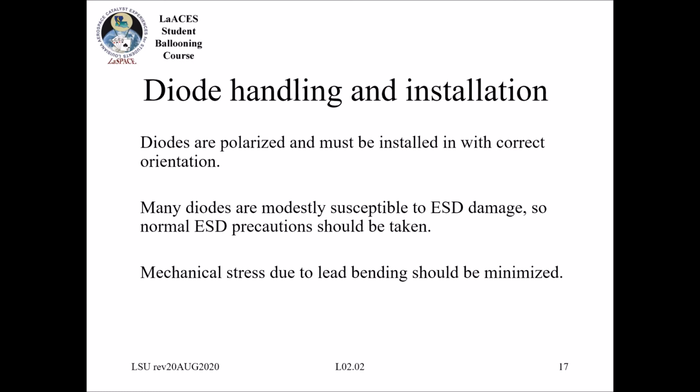The handling: they are polarized. Again, it's not catastrophic failure if you do put it in backwards, but it won't work if you don't put it in right. They're modestly susceptible to ESD damage. And then again, these look like resistors at the end of the day, and so they have the same mechanical stresses as before.